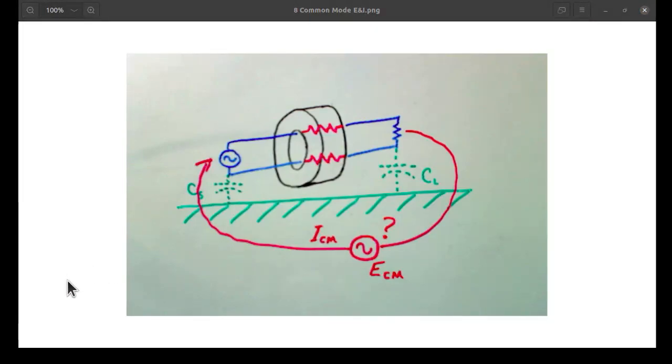Let me come back to the shack. This common mode voltage comes from the antenna itself. It's coupling to the ground. It has a potential difference between the two ends, of course, so we have a flow through the earth on that basis alone. Can't escape that. That's part of the embrace of earth.